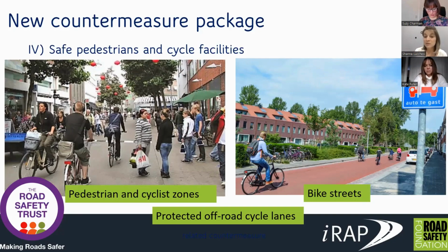So they are considered road safety measures because after the implementation, the conflict between pedestrians and cyclists with vehicles is completely minimized. This countermeasure will be triggered in urban commercial areas where pedestrian peak flows are greater than 400 and there are no cycling facilities, when the speed is low and the AADT is also low.